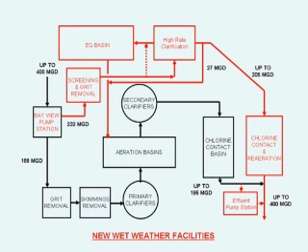a long-term control plan. The Bayview Wastewater Treatment Plant, which is a single treatment plant that serves the city, has a variety of flow conditions that it was able to manage prior to the implementation of the consent decree. The dry weather flow at the treatment plant is about 45 MGD, the annual average flow is 70. And then the secondary treatment capacity has a firm capacity of 195 MGD, so quite a bit of peaking capacity. But the collection system in Toledo is able to convey large amounts of flow to the wastewater treatment plant, up to 400 MGD with the existing interceptor system. So at times the existing treatment system was overloaded.